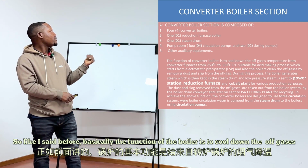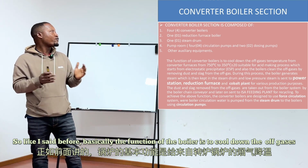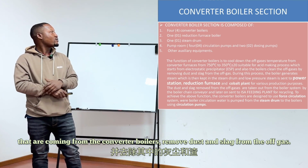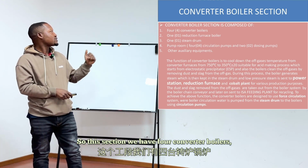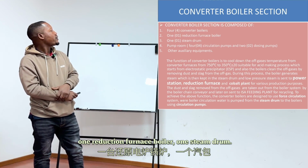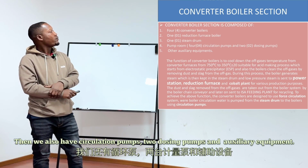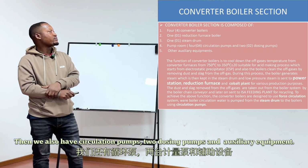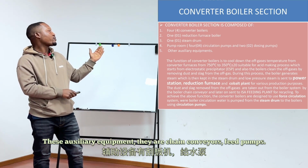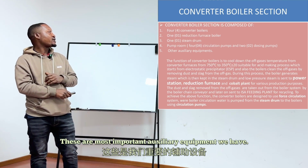Like I said before, basically the function of the boiler is to cool down the off gases coming from the converters, and to remove dust and slag from the off gas. In this section, we have 4 converter boilers, 1 reduction furnace boiler, and 1 steam drum. These 5 boilers share 1 steam drum. Then we also have circulation pumps, 2 dosing pumps, and the auxiliary equipment. These auxiliary equipments are chain conveyors and feed pumps. These are the most important auxiliary equipments we have.